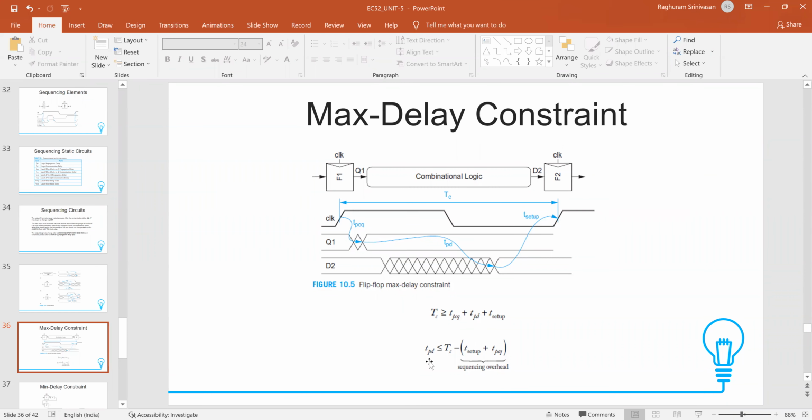So the period and this pulse width, all these things, no one can change. You cannot say, hey, give me this clock signal with period 10 and pulse width 4. You cannot do that, okay? Because for a large design, the clock signal is the same, which means the period and the pulse width are the same. So we cannot change that TC.